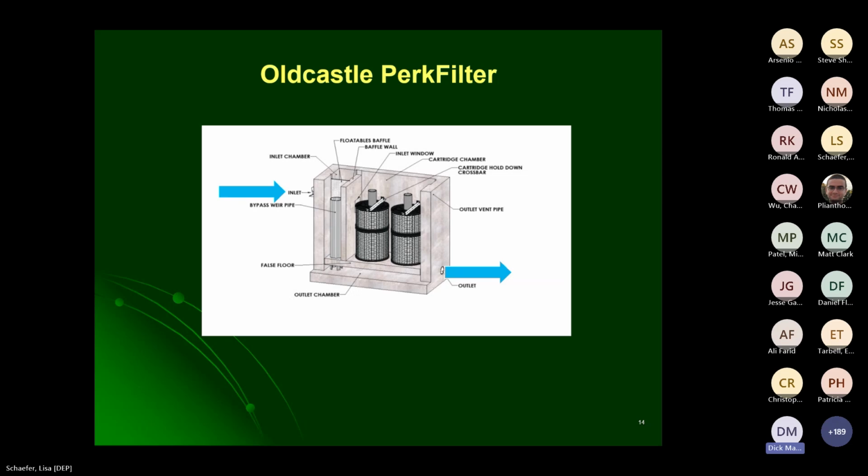But if you think about most filter type devices, they try to build in settling, and you notice those two canisters, so to speak, are sitting in a vault. So therefore, there is some sediment that gets dropped down to the bottom, fills up at the bottom, and the rest of it will then come in radially through the devices, and then eventually go down to the outside, and you'll go through the outlet. Again, 180-degree inlet-outlet device. Next slide.